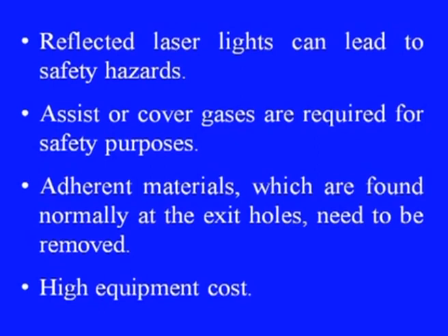Adherent materials, which are normally found at the exit holes, need to be removed. This needs additional time and involves cost. And the laser producing machines have very high costs, mainly the gas lasers and the solid state lasers.